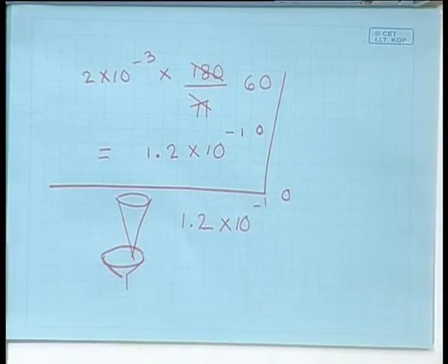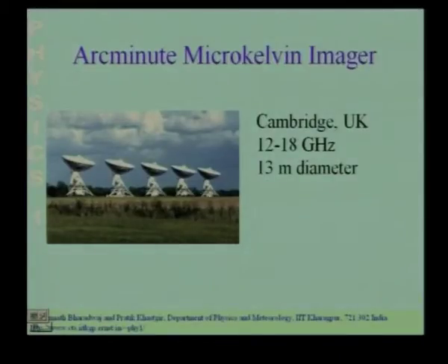Now, what is the advantage if I combine a set of antennas like this in the form of a phased array? We have seen that if I combine these radiating elements as a phased array and I do not give any phase difference between two of the consecutive elements, then it is going to emit the maximum radiation in the forward direction, assuming that there are no other maximas.